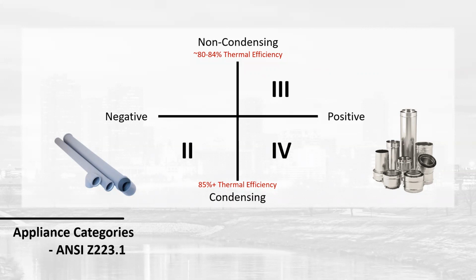So the problem with PVC is it has a very low melting point, about 155 at atmospheric pressure. And what happens is if you exceed that temperature, the molecular structure of the pipe starts to change to where it's no longer a PVC. It's just a very brittle plastic. And it has this kind of yellowish brown tinge to it. Everyone says, oh, it burnt the plastic. Basically, yeah, the molecules started moving around and heated up. So it starts to get that hue to it. You walk over, tap it with your knuckle, and it'll crack.